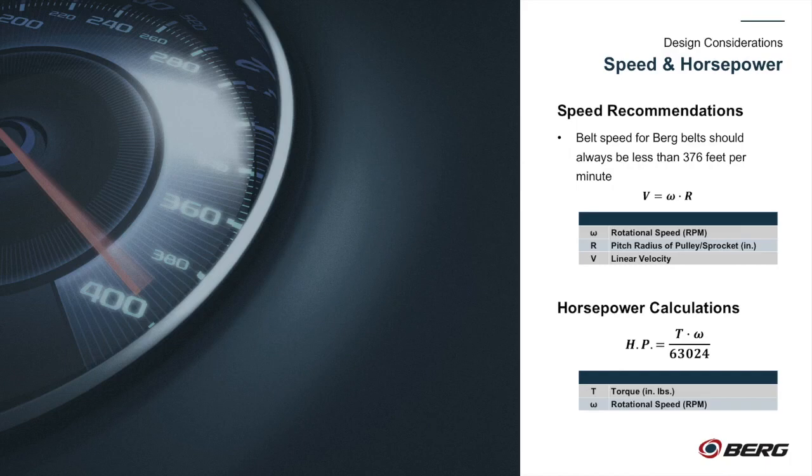Then, using this and the design speed for the selected belt, the sprocket size from the previous step can be checked to ensure that, despite the design being strong enough for torque, the linear belt speed is not exceeded. Once this is known, it is possible to calculate the horsepower of the system to ensure that the drive input is adequately selected. If the input rotational speed is lower than typical motor speeds, an additional reduction could be used to achieve the desired goals.